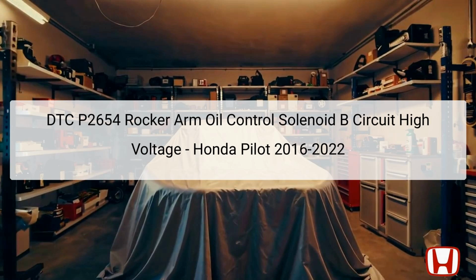The rocker arm oil control solenoid regulates oil flow to operate the rocker arms, crucial for optimal engine performance and efficiency. The solenoid is typically located in the engine bay, often near the cylinder head. Given its role, any malfunction can lead to variable valve timing issues, impacting overall engine function. Confirming this code requires detailed diagnostics to ensure no underlying causes are overlooked.